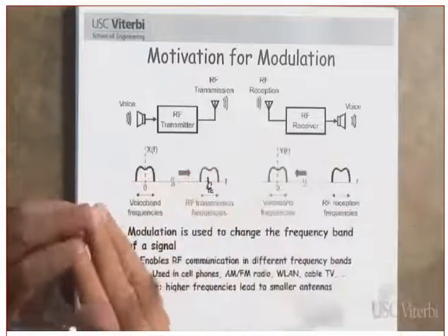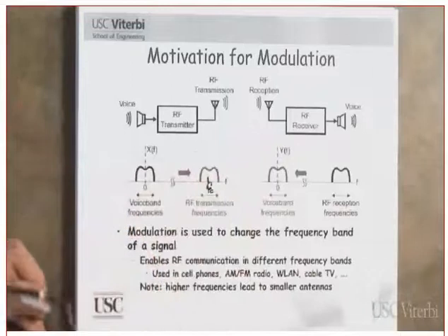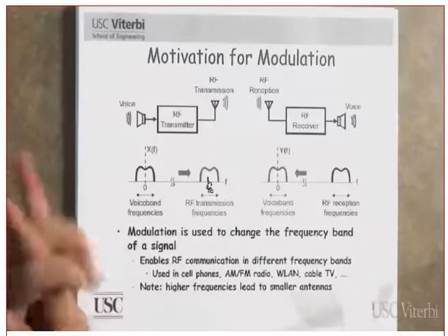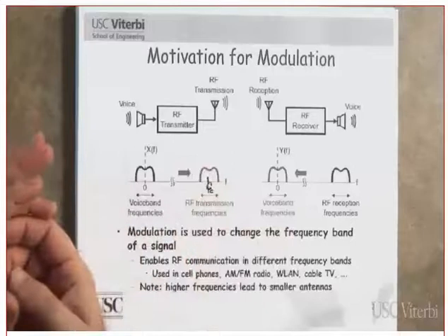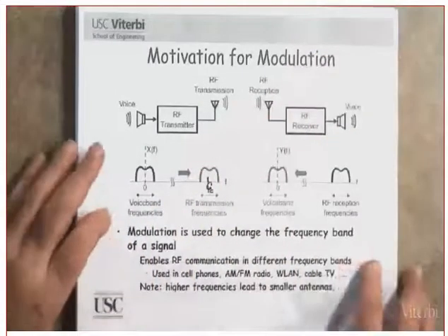Why is it not a linear operation, or the modulator in general? Because a linear system does not introduce new frequency components. Are we introducing new frequency components? Of course, that's the whole idea behind it. Clear? So keep that in mind.